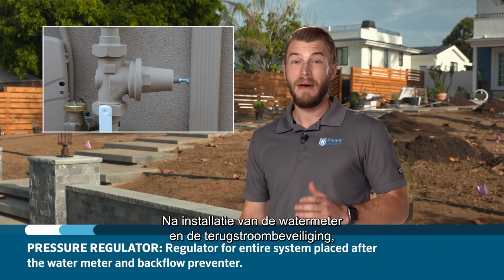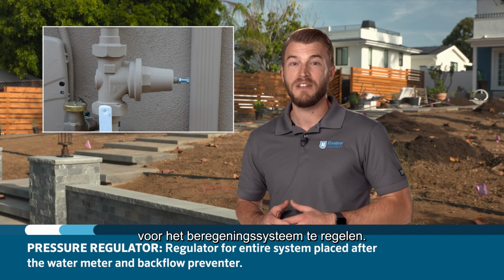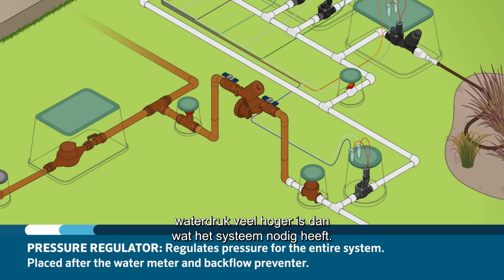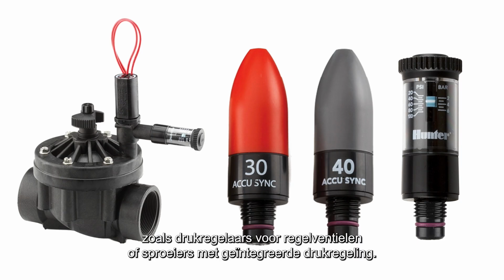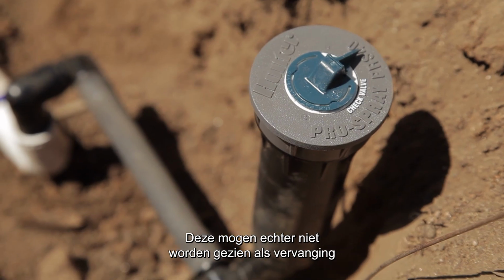After the water meter and the backflow preventer, there might be a pressure regulator to regulate the pressure to the entire system. A pressure regulator should be installed if the incoming pressure is much higher than the system requires. There are other products that can be used in the system to help regulate pressure, such as pressure regulators for control valves or pressure-regulated sprinkler bodies, but those should not be a substitute for pressure regulation at the point of connection.